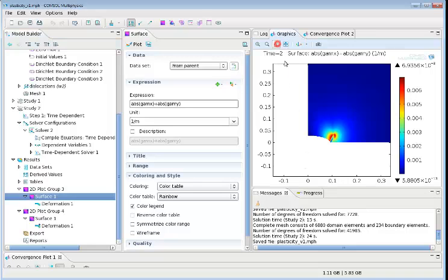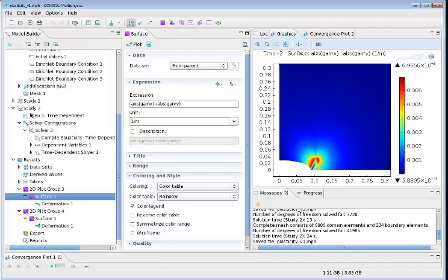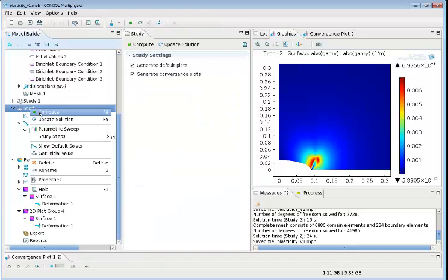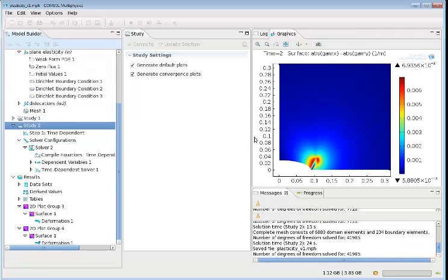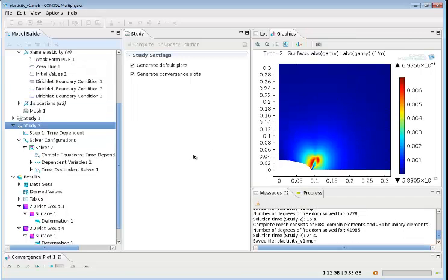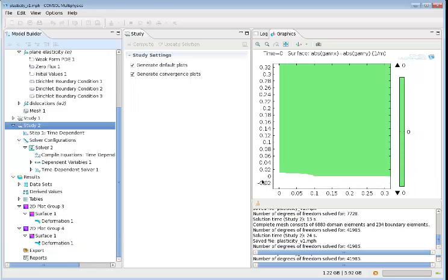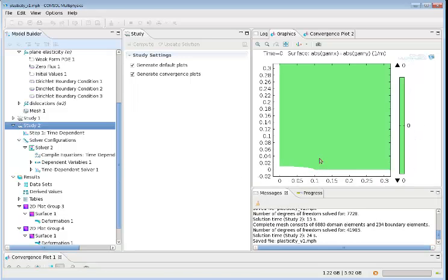So you're going to see initially no dislocation density, so it's going to be fully zero or green. And at some point dislocations will start propagating in. That's because right now the shear stress hasn't reached the critical shear or the yield. Right here it does. And as we continue pulling, that plasticity zone starts growing.